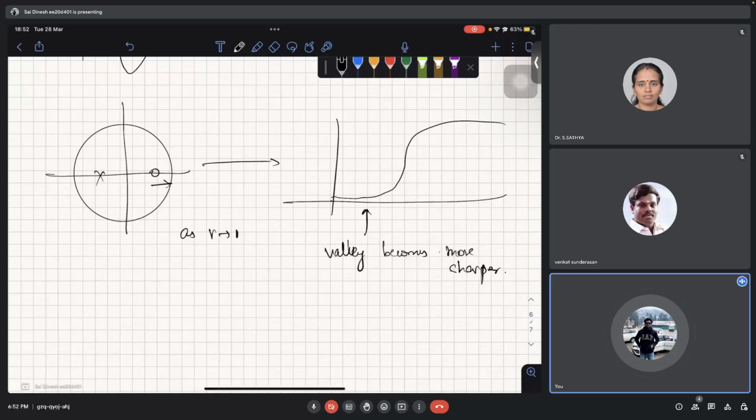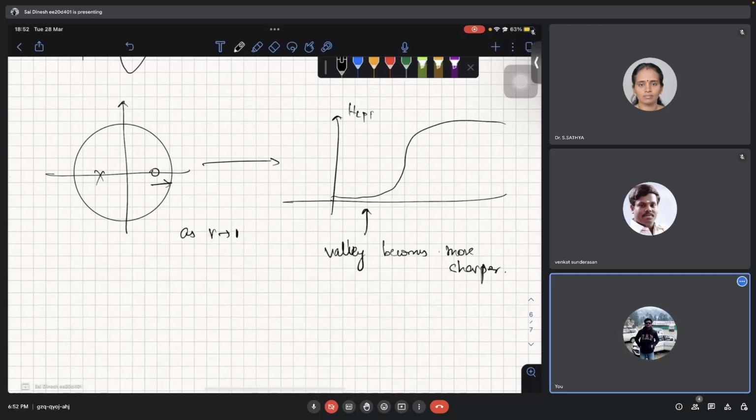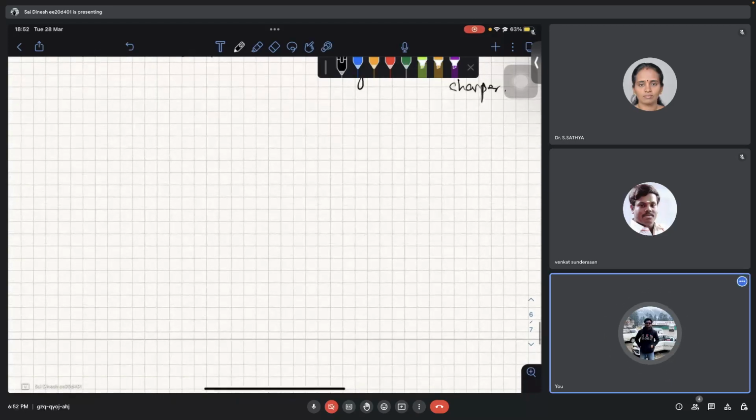So this low pass filter's magnitude response, because of the zero, and that too if it is very close to 1, the closer it gets to the unit circle, the sharper it becomes. So I think with all of this we get the answers directly. All these questions are straightforward just by looking at the magnitude response of a single complex pole or zero.